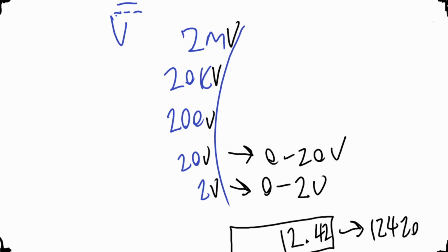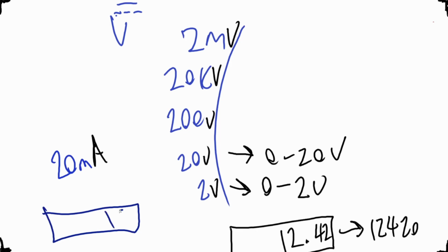Because what you might be doing is measuring the current in 20m, lowercase m. That means milliamps. So you're measuring in 20 milliamps. If you measure in 20 milliamps, again equivalent to measuring in 20 volts or something, watch out, because the multimeter might display something like 15.